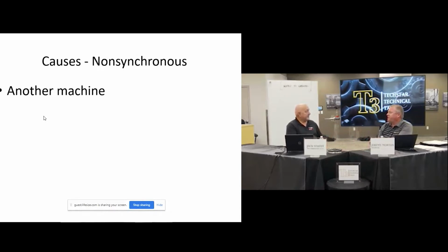So if the machine can't be shut down, I guess that would be an instance where you would need to use something like a strobe light. Yes. Using a strobe light, they have one designed for vibration analysis, where you tell it you want to track the 1X on it. It will track it, and that way you can do order tracking. Okay, your synchronous analysis. Gotcha.